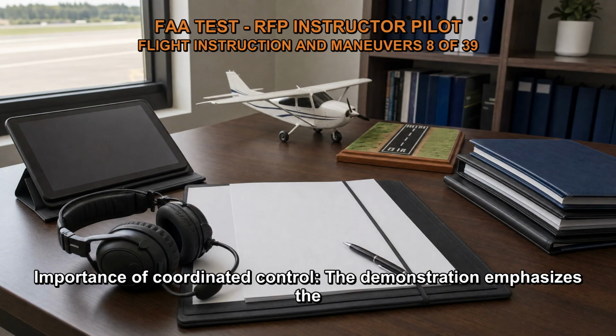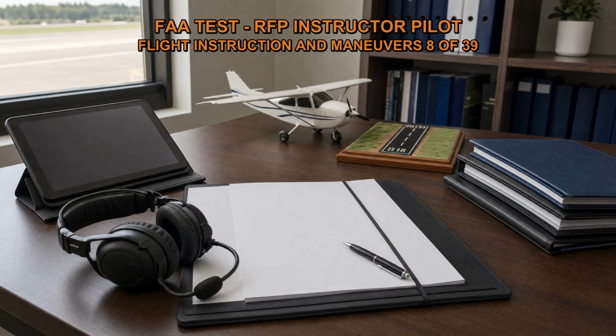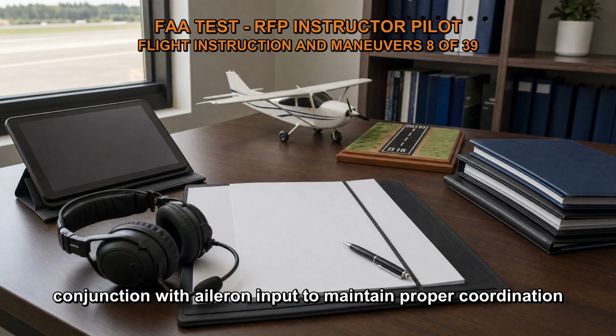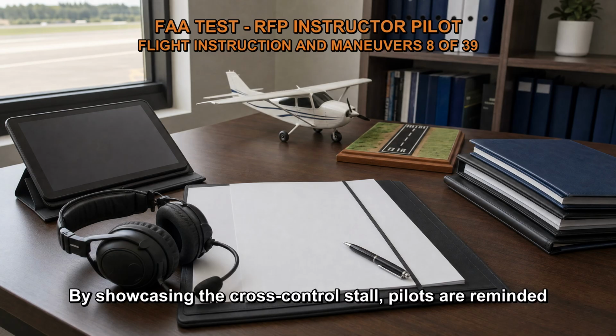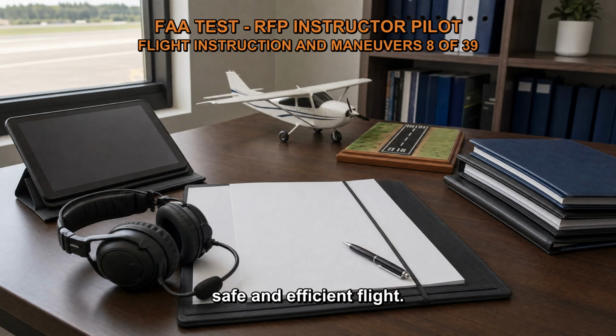Importance of coordinated control. The demonstration emphasizes the importance of coordinated control inputs when making turns. Coordinated control means applying appropriate rudder input in conjunction with aileron input to maintain proper coordination and prevent adverse yaw. By showcasing the cross-control stall, pilots are reminded of the need for coordinated control to maintain safe and efficient flight.